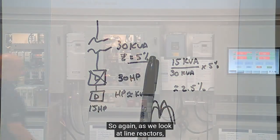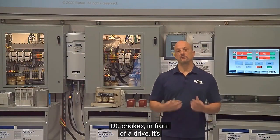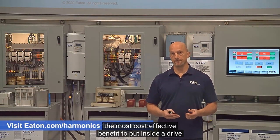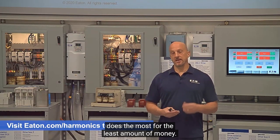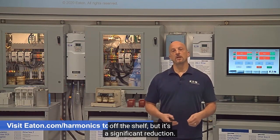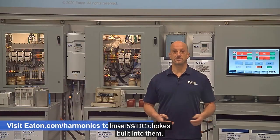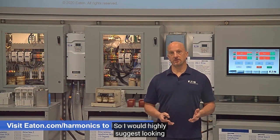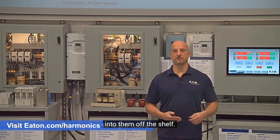So again, as we look at line reactors and DC chokes in front of a drive, it's the most cost-effective benefit to put inside a drive or in front of the drive, because it does the most for the least amount of money. It doesn't get you below the levels maybe of IEEE 519 off the shelf, but it's a significant reduction. And all of our DG1 drives, for example, have 5% DC chokes built into them. So I would highly suggest looking at buying drives that have that impedance built into them off the shelf.